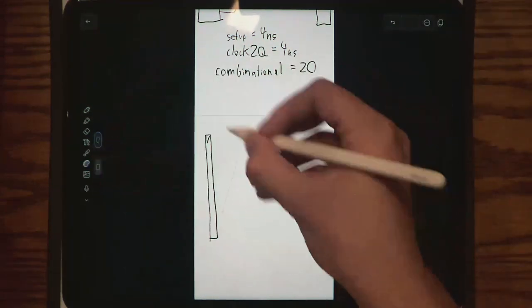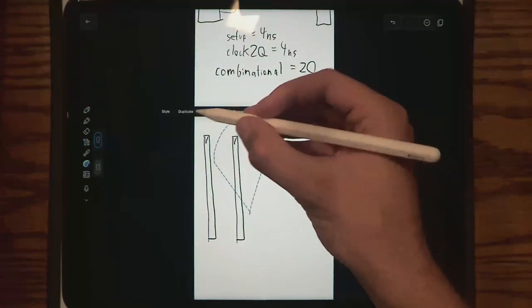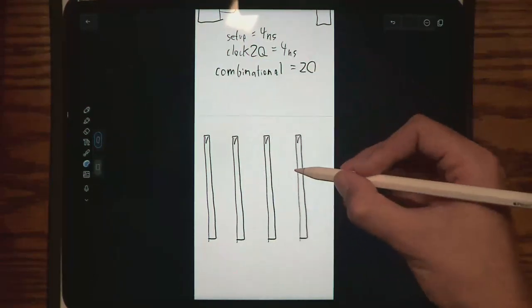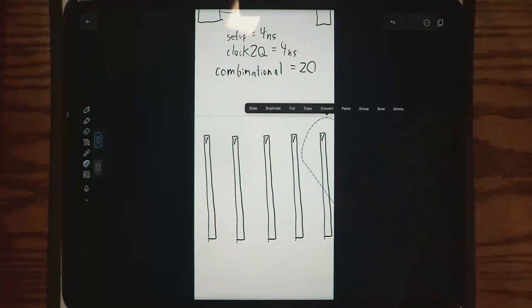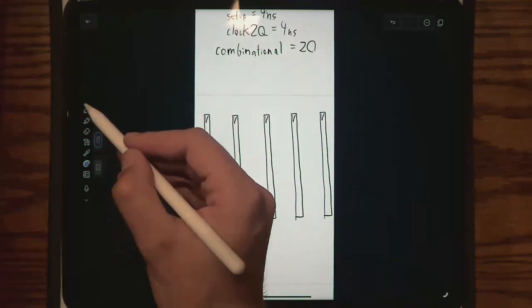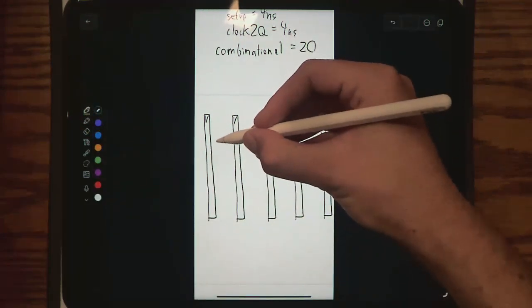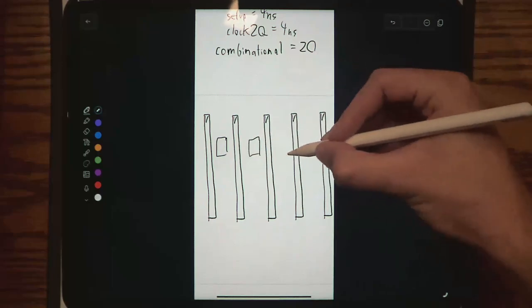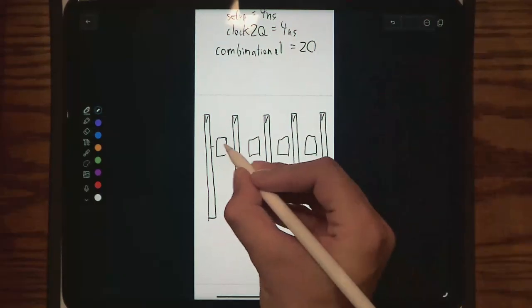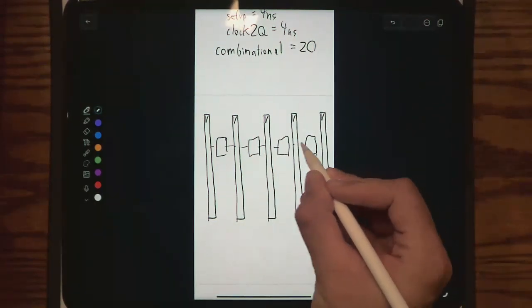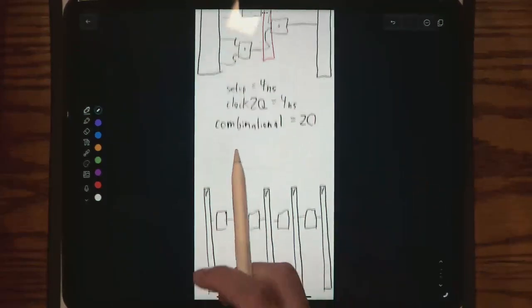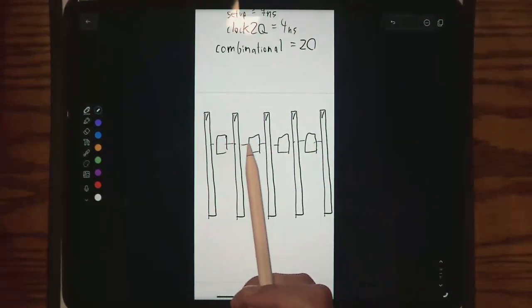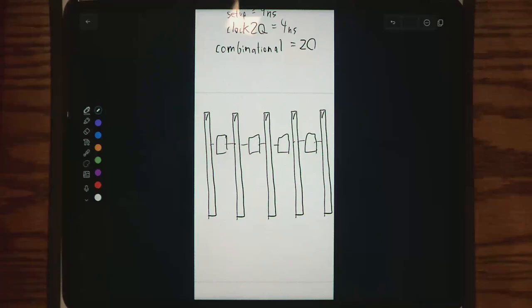In modern processors, you might have anywhere from 4 to 20 pipeline stages in any individual cell that you have. So maybe you're doing some logic here, and then logic here, and logic here, and through each of these stages it propagates through. Originally, it would have been a very long amount of time if you wanted to perform all of this combinationally in one single clock cycle. But now you can perform just little chunks of it. And so now your clock frequency goes up.